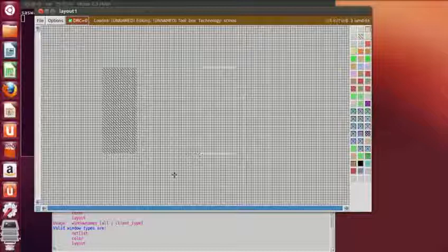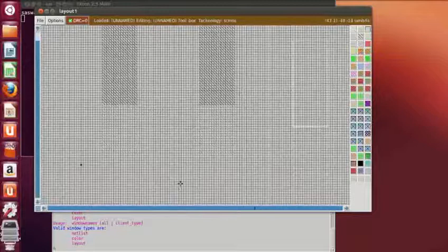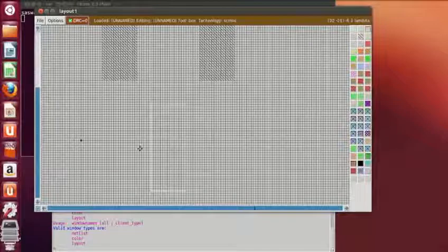Since this is an AND-OR-invert, the AND means the NMOS is in series and the PMOS will be in parallel. So this is one PMOS, this is another PMOS. So middle click on the nwell, and the third PMOS will be in series with these two PMOS.